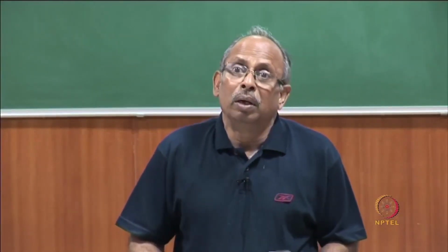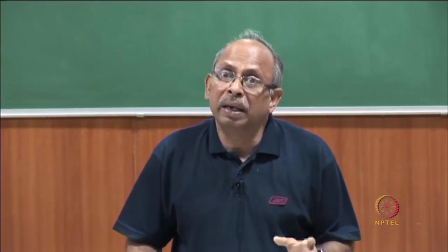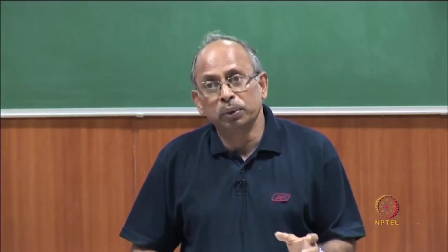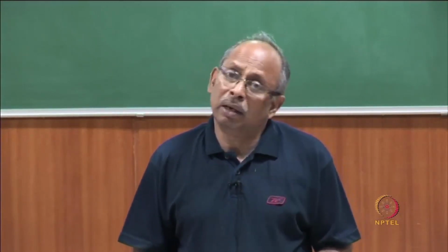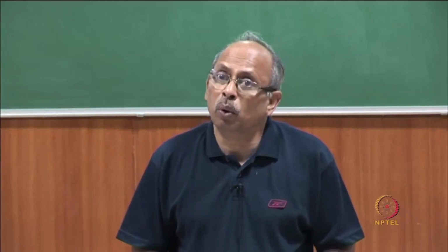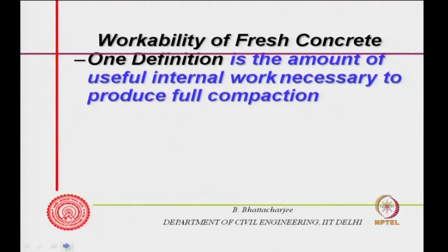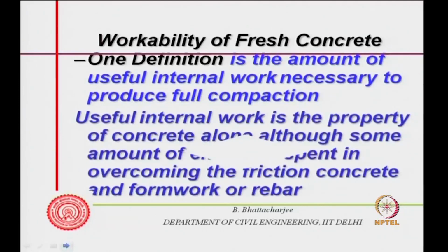So, therefore, workability is defined as the amount of useful work required to produce full compaction, and we also said that concrete seldom conforms to the shape of the mold. Therefore, some amount of mobility is also involved. So, workability is the useful internal work necessary to produce full compaction.